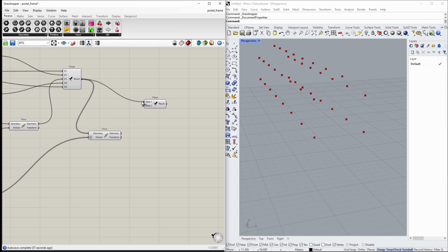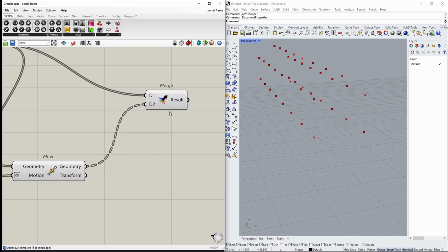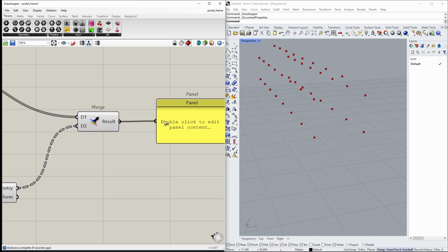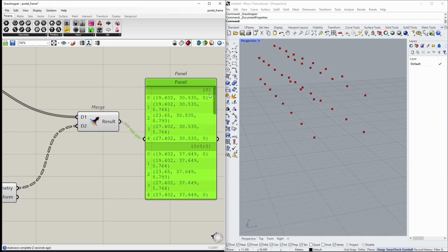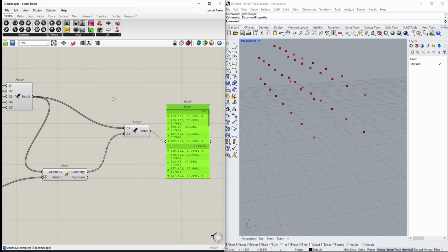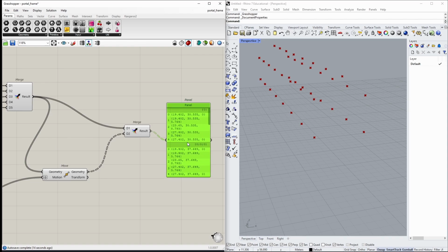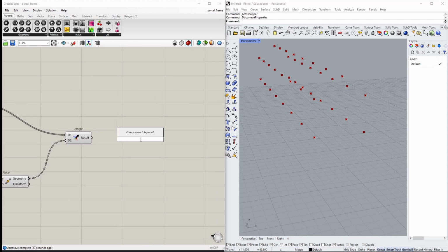But by simply merging these together, the difference in the structure that the two lists give us will result in unnecessary complication in the future, which we do not want. This happens because Grasshopper took the two lists and simply glued them together. The fix is a pretty nifty tool called Path Mapper.